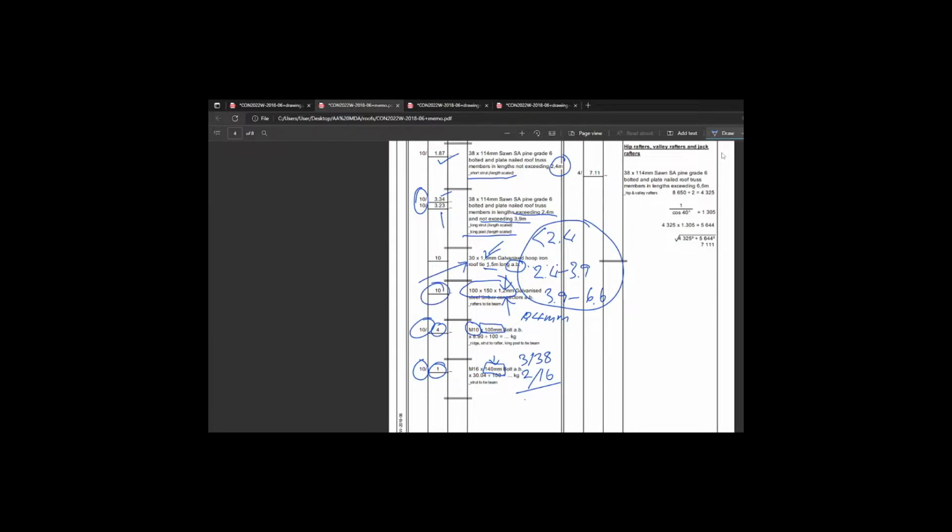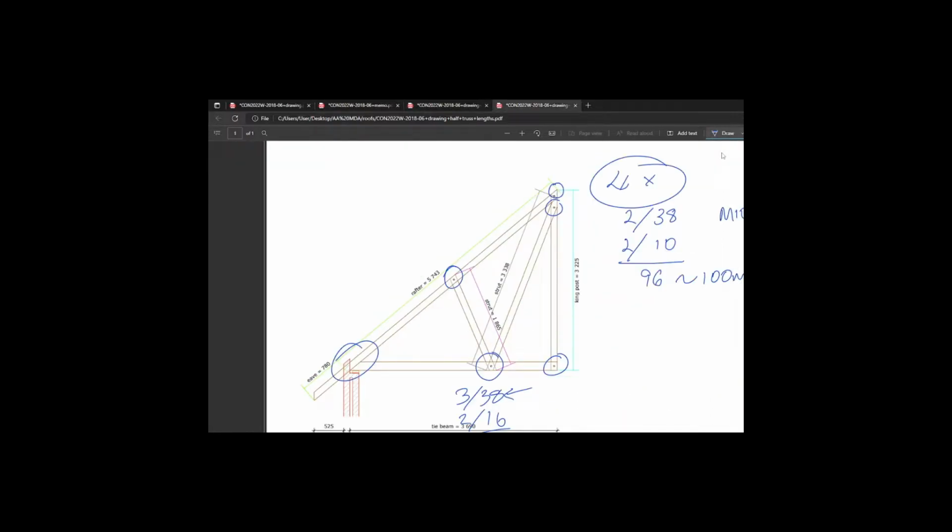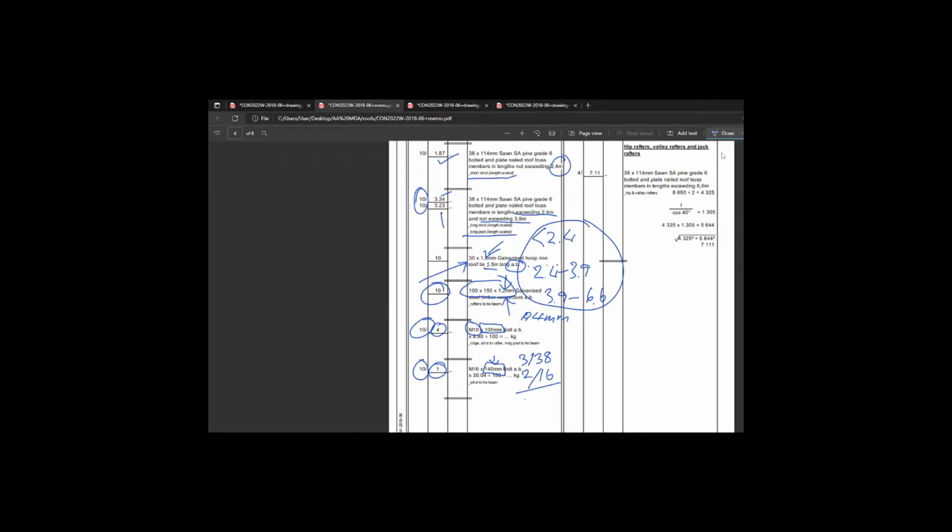We'll go back to the nail plates, the steel timber connectors. We've said there are 10, let's take a look here quick. So, as I previously said, in the absence of an indication as to what is connecting the members, we assume it's a nail plate. Bolts everywhere else, because there's your dots. But there's a nail plate here, 100 by 150, 1.2 millimeters. Told you, I forget this, 1.2 millimeters. Anyway, same rule here.